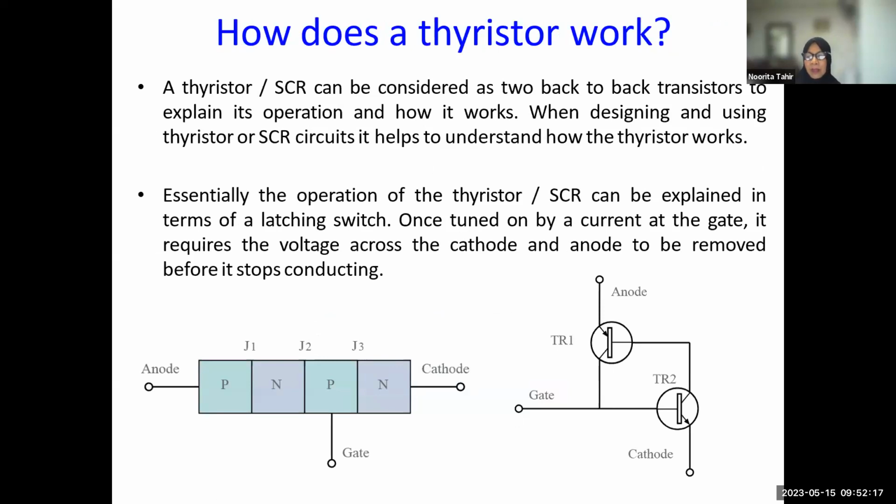The way in which a thyristor operates is different compared to other devices. Normally, no current flows across this device. However, if a supply is connected across the device, and a small amount of current is injected into the gate, then the device will fire and conduct. It will remain in the conducting state until the supply is removed.